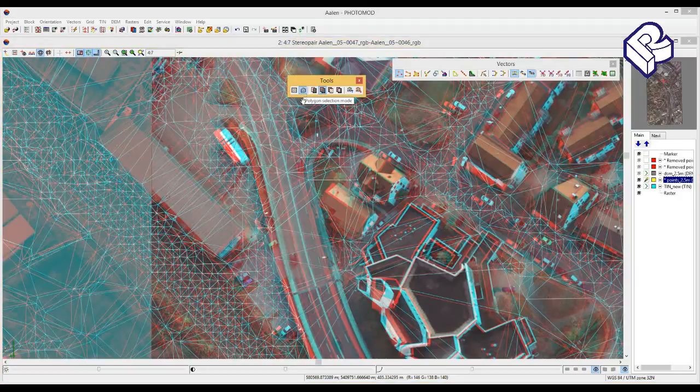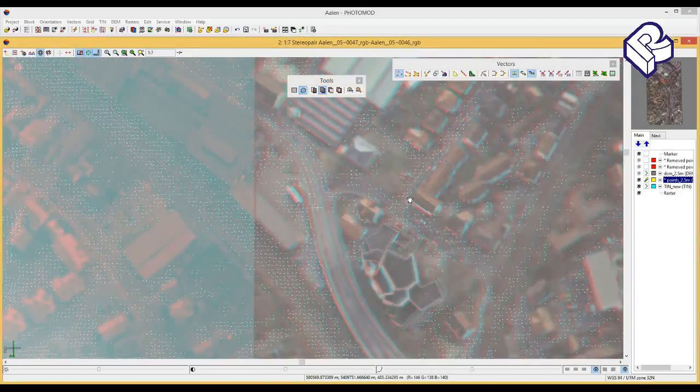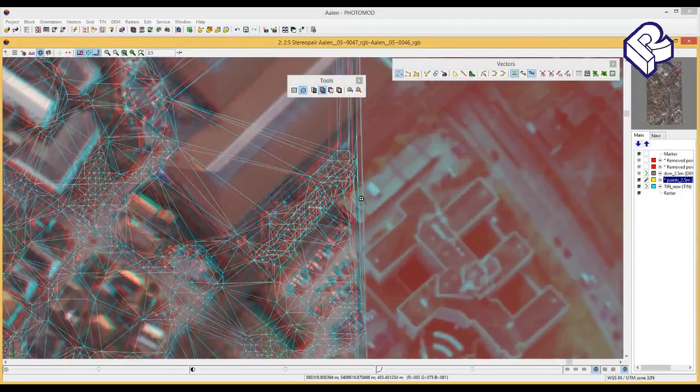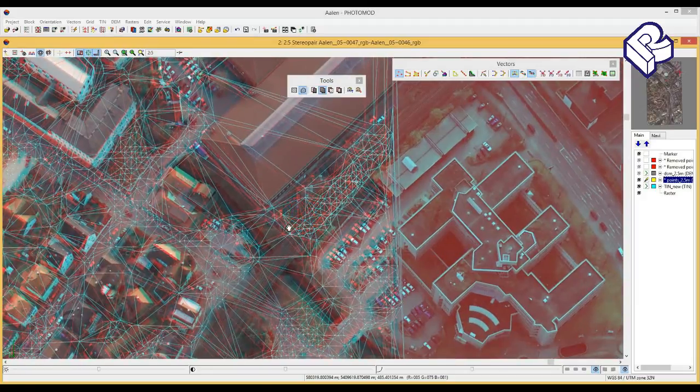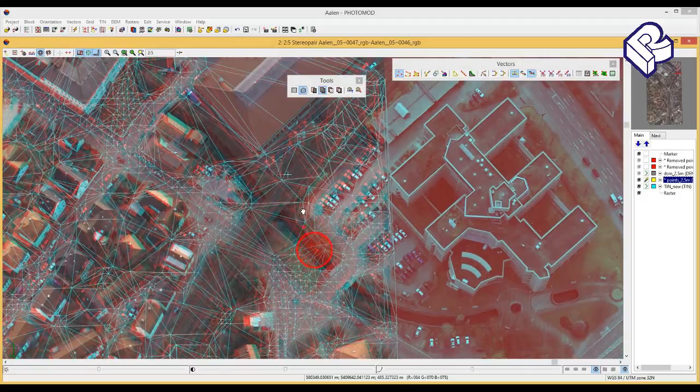In addition, I may select Polygon selection mode in order to select a large area of problem 3D points at once. I keep the Shift key of the keyboard pressed and draw the configuration of the area that should be deleted, and press the delete key. The TIN model is rebuilding simultaneously.